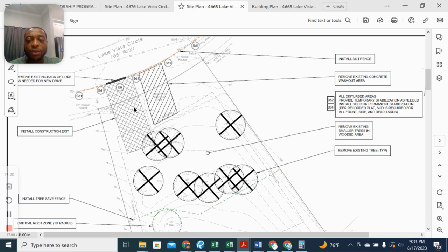Okay. And I will show you the makeup of it. It is actually a geofabric, something that looks like the silt fence that goes down here first, and then aggregate goes on top. In this case, we put stone on top. Okay. I'll show you that. You see in the video. And that establishes your construction exit so that when vehicles, equipment come on here and there's dirt and mud here, when they're leaving, it will stop all of that mud from being tracked out into the street. So it minimizes that. And if you get mud and dirt in the street, you have to clean it up.